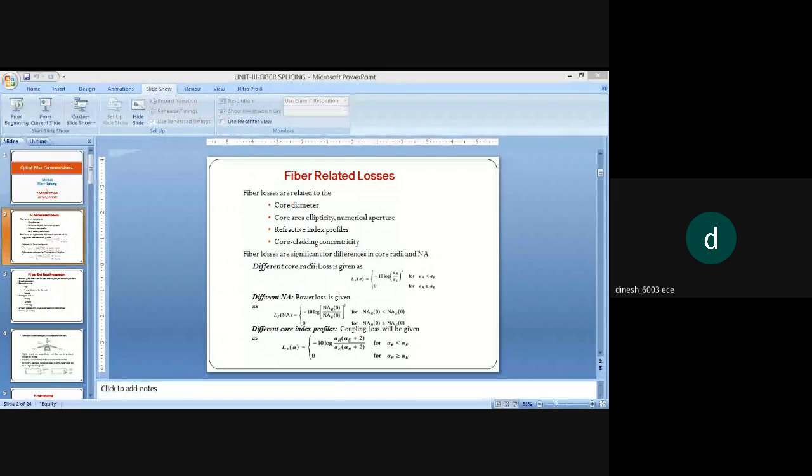Improper tension can cause multiple fractures and leave a damaged end face, such as a smooth end face with a lip, a smooth surface, or a hackled surface. These tend to break. One way to avoid this is a methodology called splicing. There are three different types that can be done: first is fusion splicing, second is mechanical splicing, and third is elastic tube splicing.